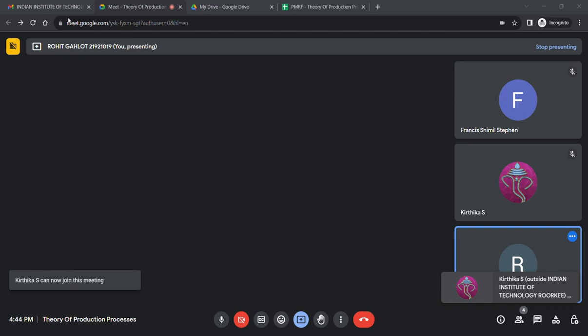Okay, this is taking many times, so let's solve this. Firstly, these are the given things. The volume of the casting is 80 times 120 times 20 mm, and H is equal to D. The solidification time for the casting is 2 minutes, for which K is equal to 2.